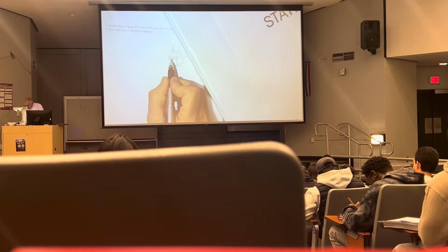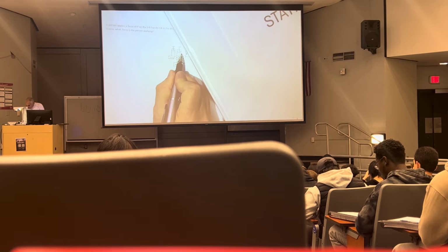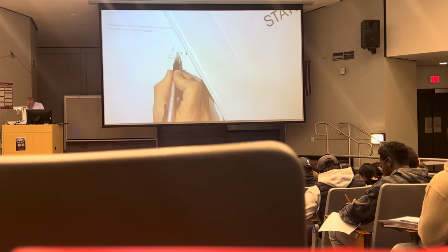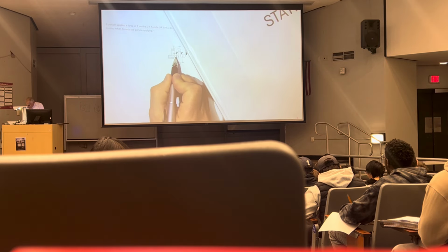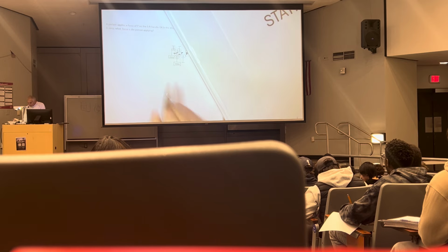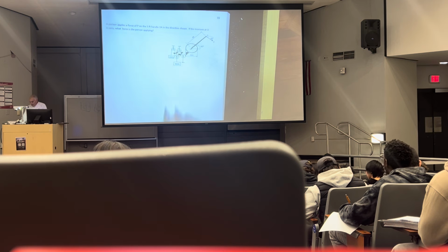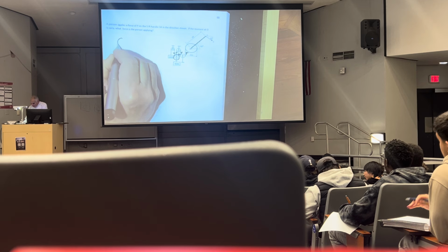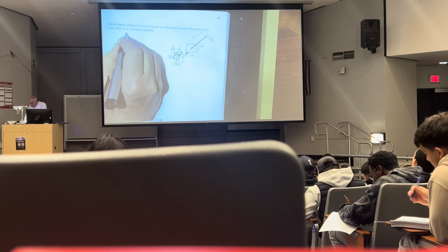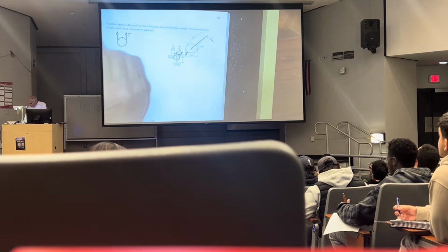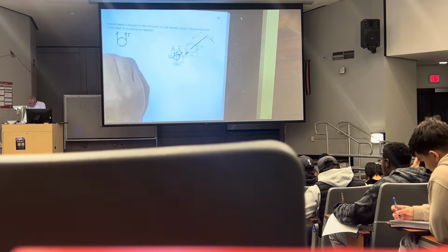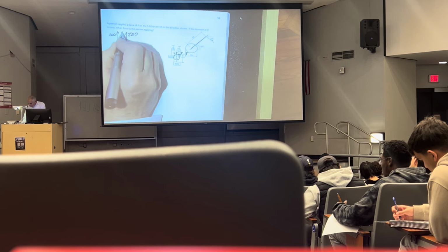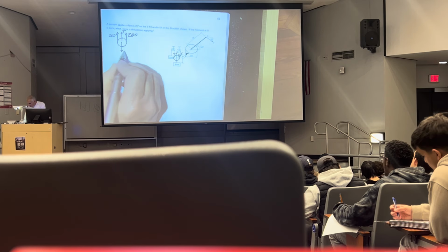If I look at this and I say that's P, let's call it T. That's T, that's T. This is 200, that's 200. So if I isolate this right here, I'm going to get this pulley to look like this as a free body diagram. 200, 200, T, and downward is going to be 800.